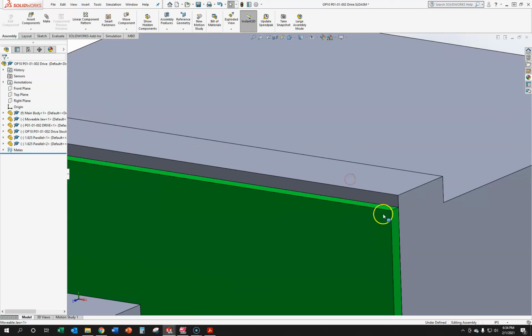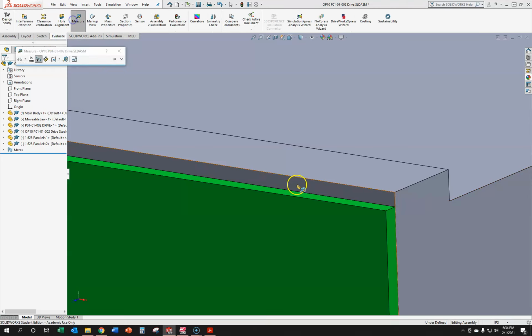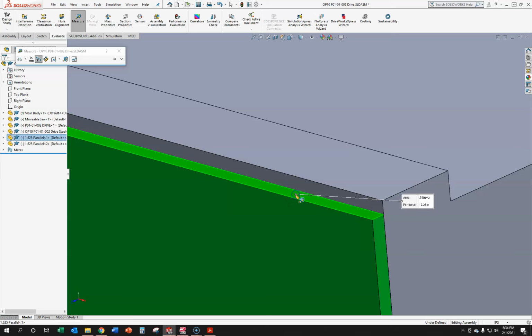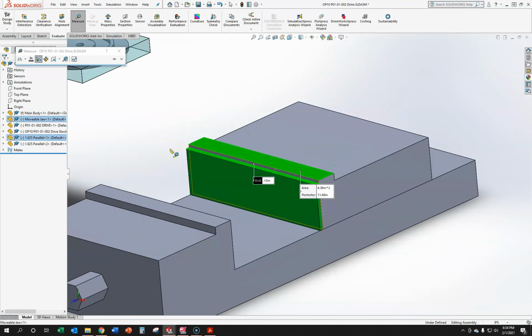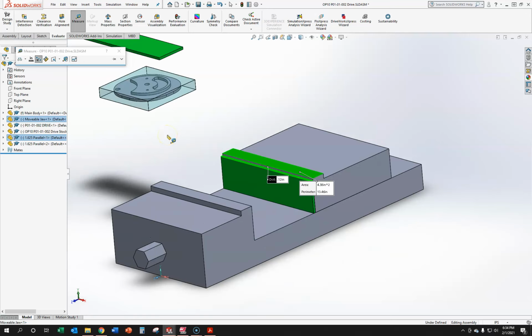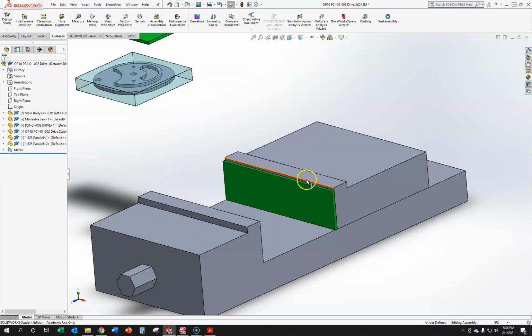And then you can see it. So this is the height of the work holding that we have on this. And it looks very slight. So I don't know, maybe we'll modify this. We'll go check this. So that's only 1/8 of an inch in the vise. We'll take a look at it. Maybe we'll modify it. We'll see what happens. That is not a lot of work holding material there. So basically what happens is you're risking the part coming out of the vise.